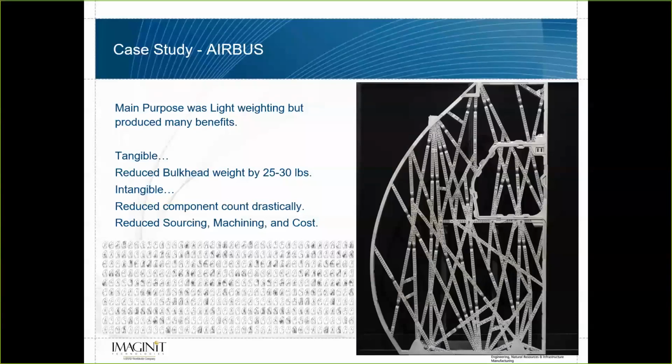So again, we can see quite a few variations came of this, but realistically, when you start looking at what this bulkhead needs to be, you probably don't care too much about some of the mesh things inside of it. Obviously, if you have wires that need to route somewhere, you're going to pick an option where the wires can route through, while other existing components can bolt to it, things of that nature. So there's still some thought process that goes into it. But in general, reducing that weight and keeping the stiffness and stability or strength high on this component were the main goals.